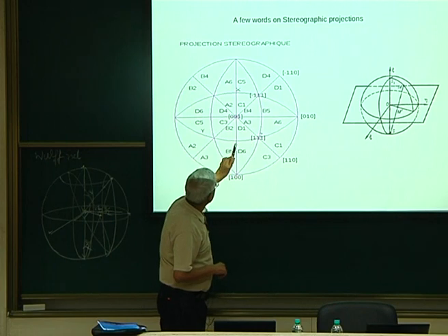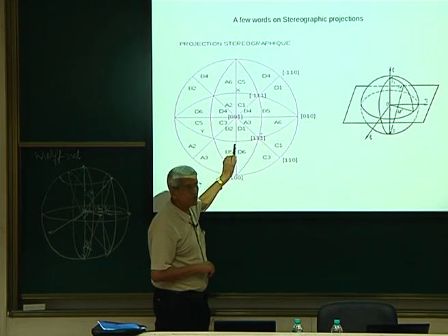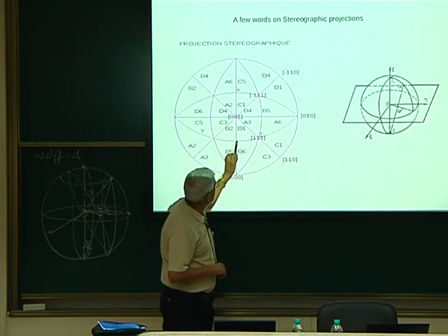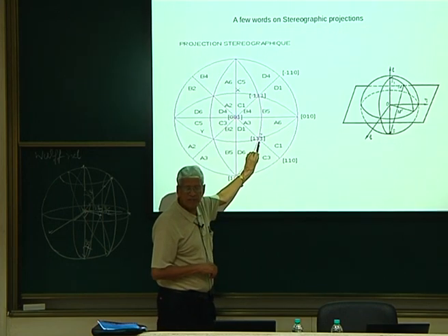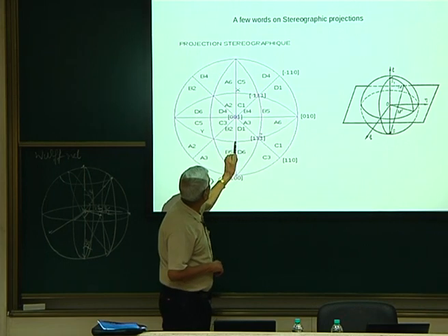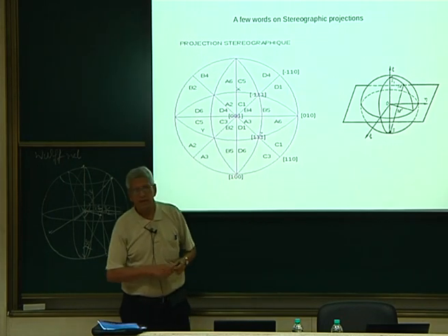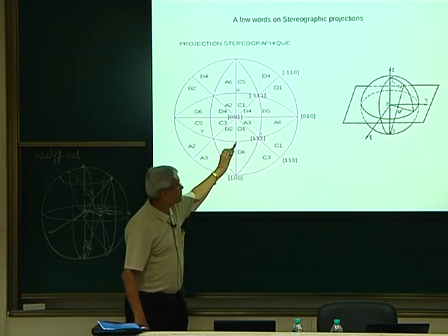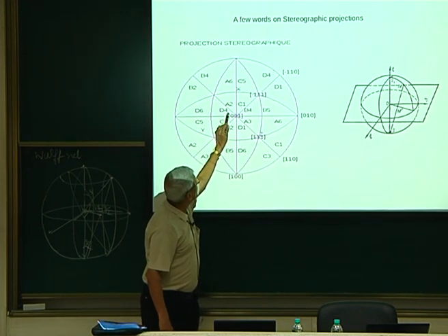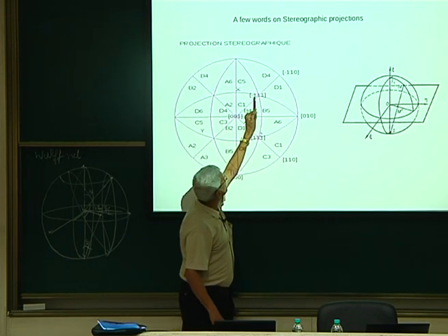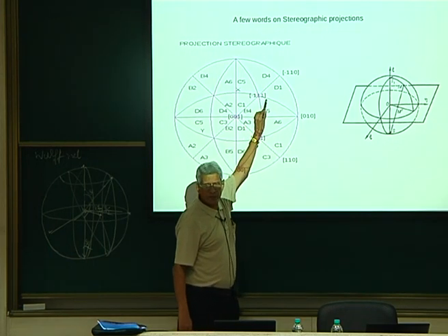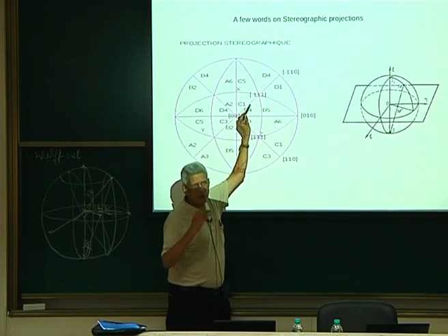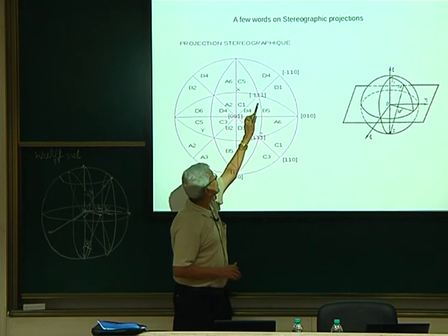Then this is 101. With respect to 101, if you consider it, this is 45 degree, this is 35 degree, okay, 36 degree, and from here to here it is 60 degree. So for this particular one, and with respect to 1 bar 1 bar 1, this is a plane normal, which is normally called in stereographic projection as a pole in the projection.